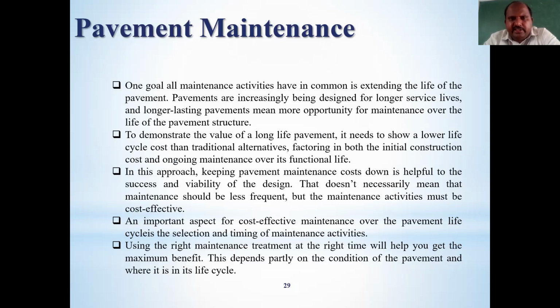To demonstrate the value of long life pavement, it is needed to show a lower life cycle cost than traditional alternatives, factoring in both the initial construction and the ongoing maintenance cost over its functional life. In this approach, keeping pavement maintenance cost down is helpful to the success and viability of the design. That does not necessarily mean that maintenance should be less frequent, but the maintenance activities must be cost effective.